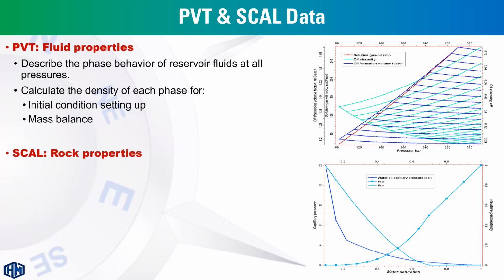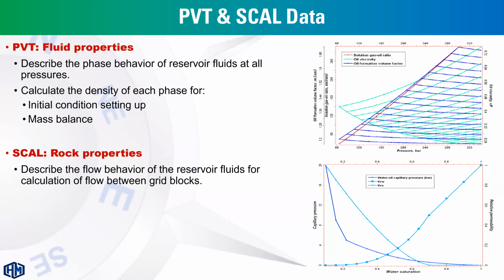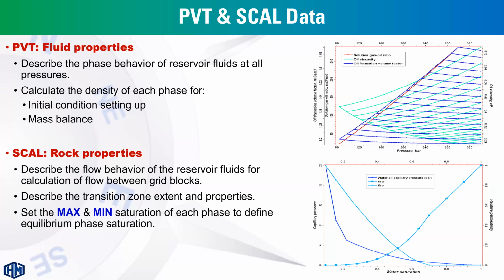The SCAL or rock physics functions are required to define the transition zone between the free oil and free water zones, and also to define minimum and maximum saturation for each phase for every grid block.